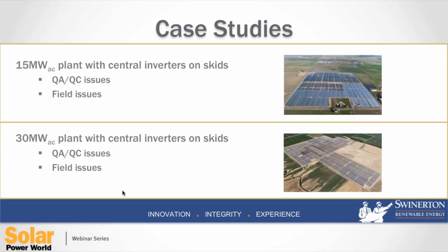And we set up a number of different mechanisms through a plant controller setup like Jeff described, where the utility can control things like power factor and curtailment, ramp rates. It's no longer looking at the inverter level for us. We're now looking at controlling our sites at the point of interconnect, while the inverters make up a huge piece of that ability.